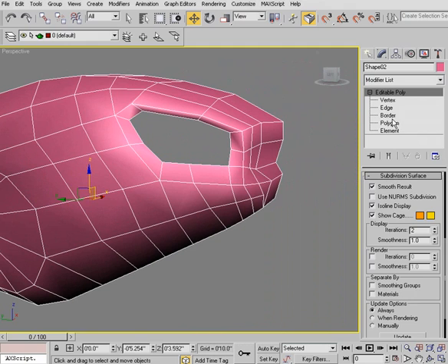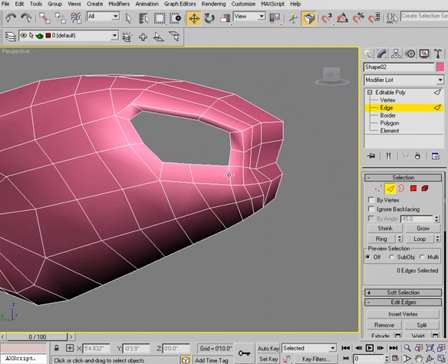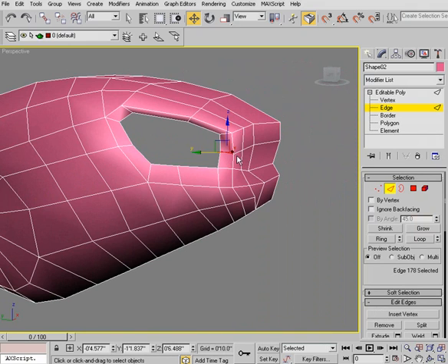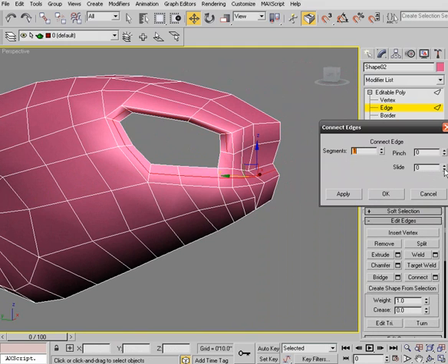We could use our connect. So we could select this ring. In this case, I'm going to start here because it's going to cross over each other. I'm going to hold down Control and click on the up arrow on ring, and that'll take that selection up until we get to the end. And then I can come in and add connect and slide that out to the outer portion there.